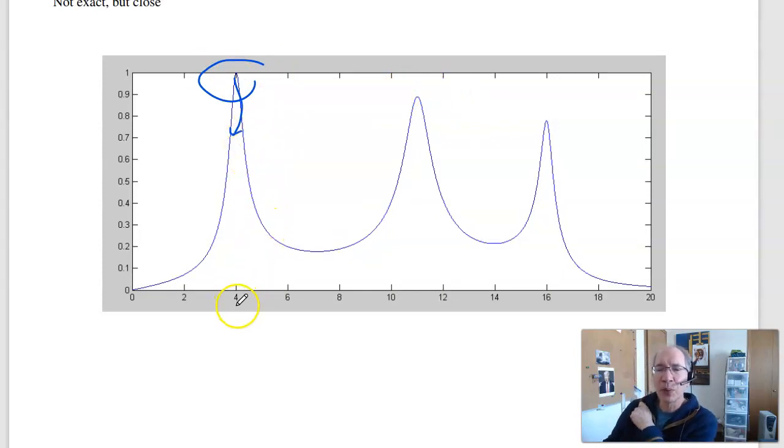I want to bring that down a little bit, and I could do that by adjusting the real part. I've got a pole at j4. As I move it closer to the j omega axis, this gets bigger and bigger. If it's too big, I'll move it away from the j omega axis. That'll bring that point down. But it's kind of got the right shape.